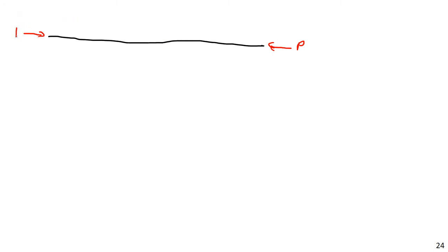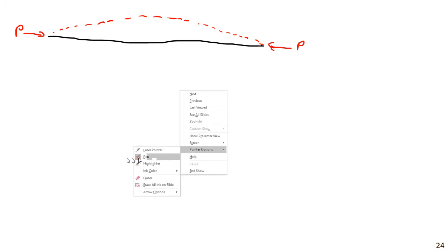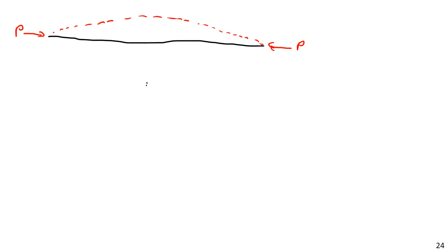Well, it tends to buckle, and we'll talk about buckling load in a couple weeks when we get to compression members. So we can have buckling here, popping out and failing. In Euler buckling, for example, you get failure long before you have the actual ultimate load or the elastic limit, etc. But with tension members, that doesn't apply.